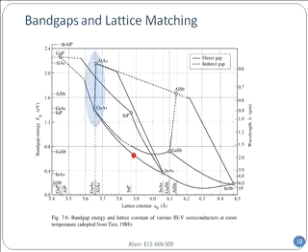Do you see the bow-shaped line and the red point sitting in between? So you'll have to take a combination of indium arsenide and gallium arsenide, mix them, and then have a material whose lattice constant is just about right for indium phosphide. And then on top of it, grow indium phosphide.